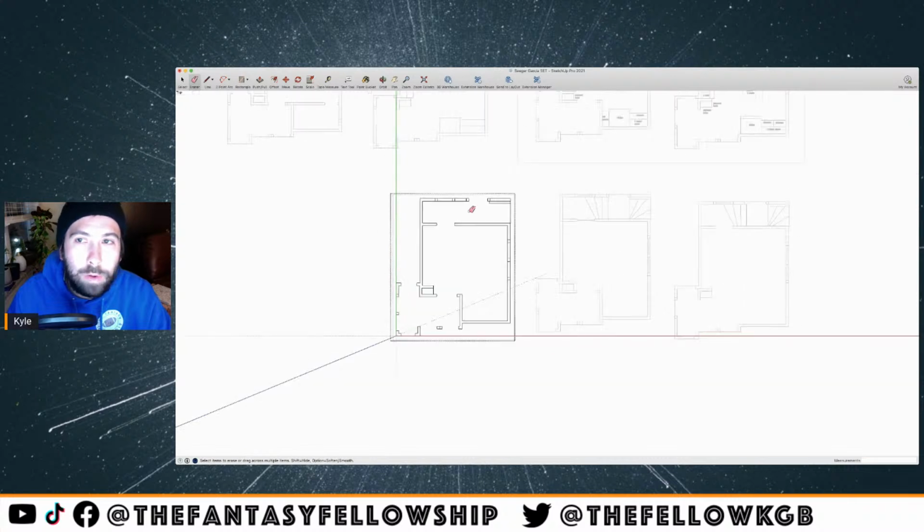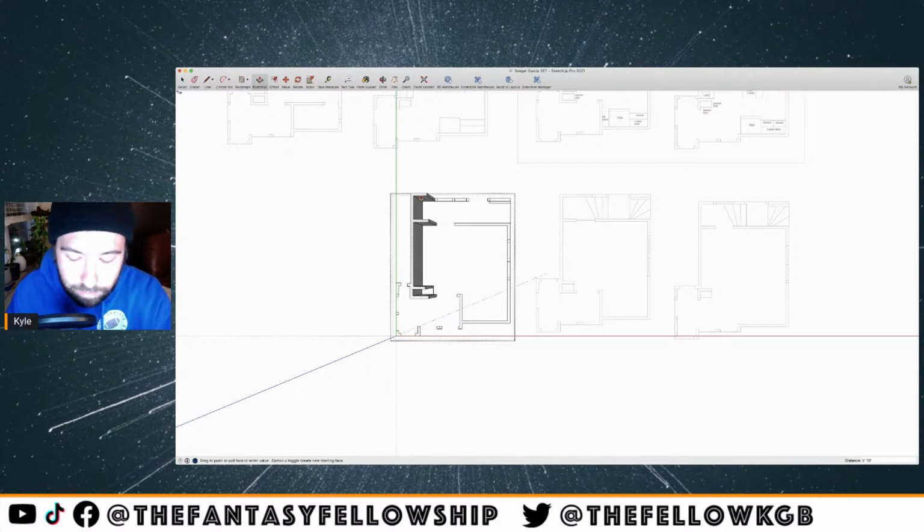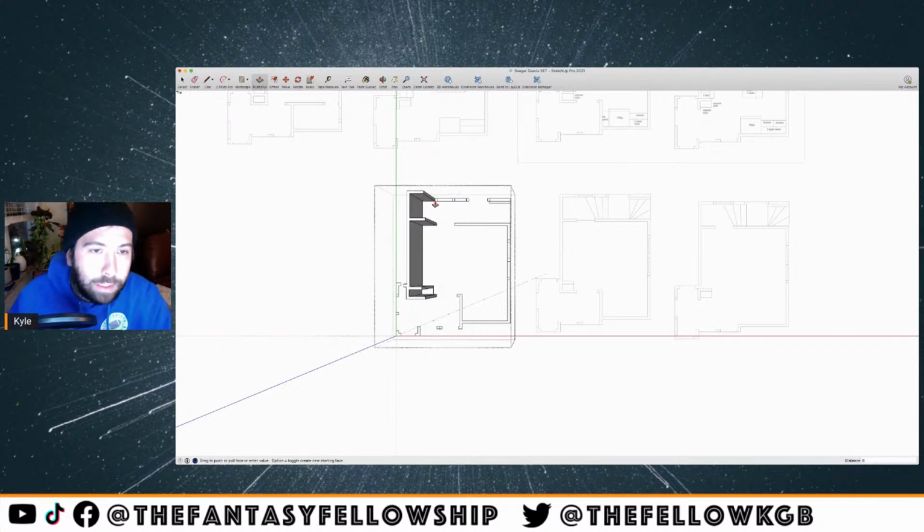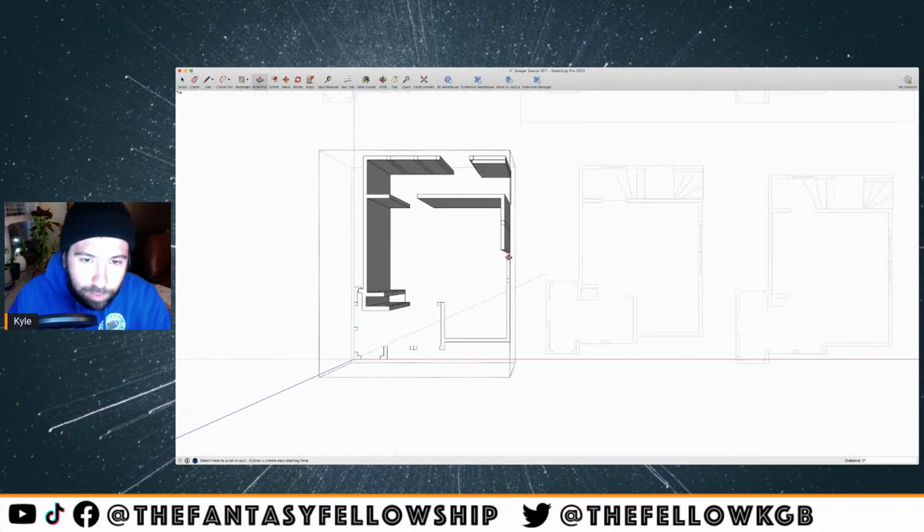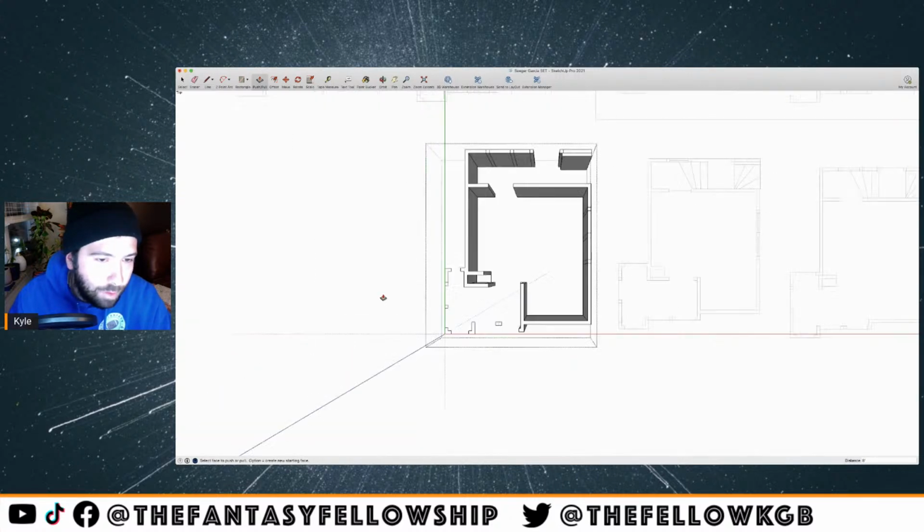At the moment, I'm going to draw this with 8-foot tall ceilings. So I used my push-pull tool, which is up here in my toolbar. I click on it, and then I can pull up my walls. I'm going to type in 8 with the foot mark here, and now I can snap everything to 8 feet. I'm just going to go through and click on all my wall faces here. It's pretty simple to pull things up into 3D, especially when you have them already drawn for you.